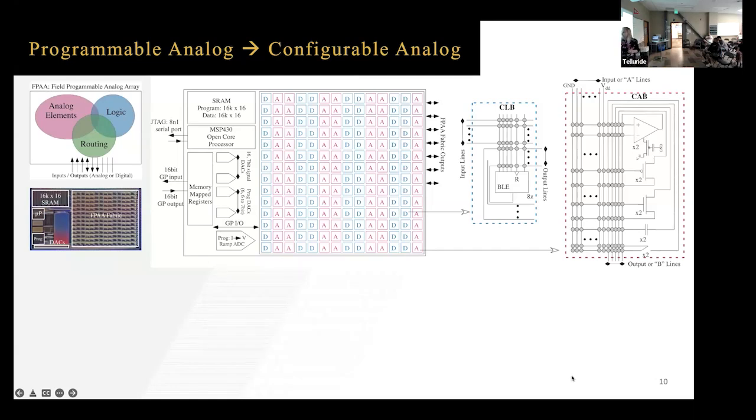This is the die photo of it. This is the fabric. The microprocessor is a little block here. But the next biggest element in here is basically the SRAM. And that's only 16K by 16 of SRAM. Granted, it's a 350 nanometer CMOS process, but I will tell you as we looked at this across smaller nodes, getting the same sort of compilation, that ratio will get even better for the most part. And so one of the first things you realize is memory is expensive. SRAM memory gets expensive on you.